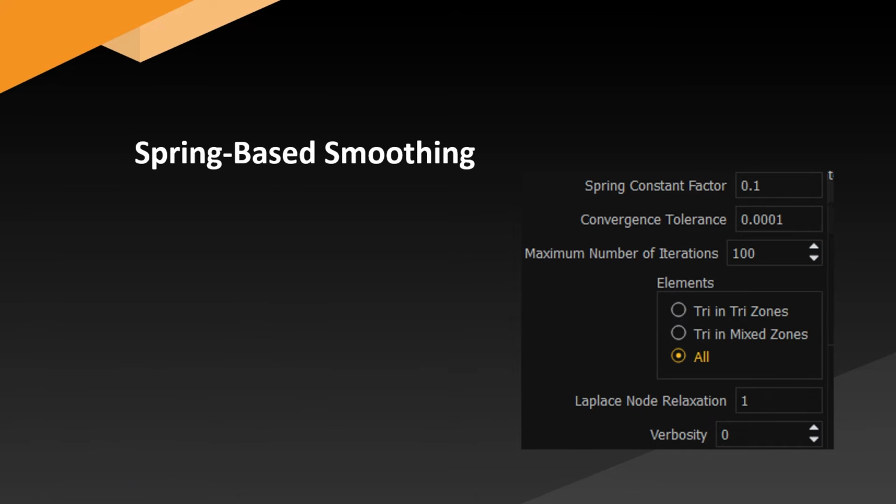In general, the software solves the previous equation iteratively during each time step until one of two cases is established: either the number of iterations that we set is over, which is determined by the maximum number of iterations option, or the solution converges in that time step, where the convergence limit is determined by the convergence tolerance option.